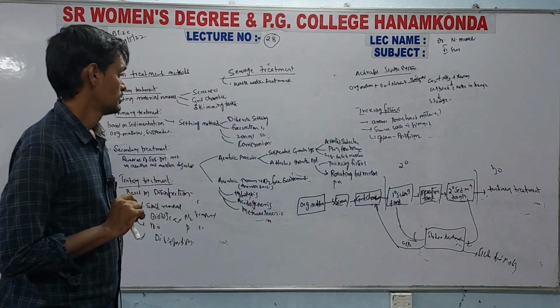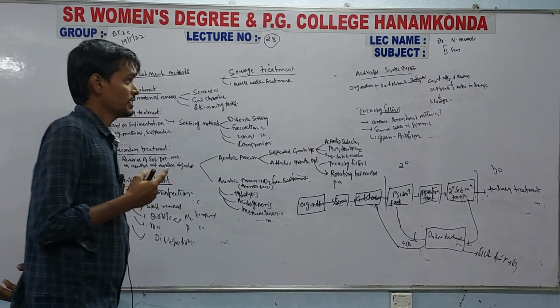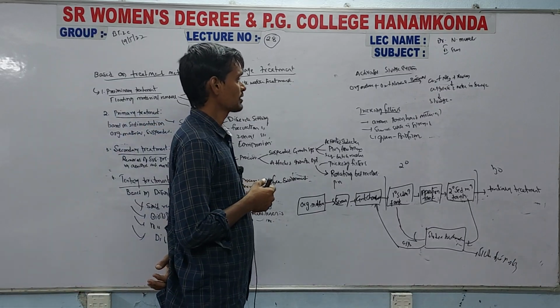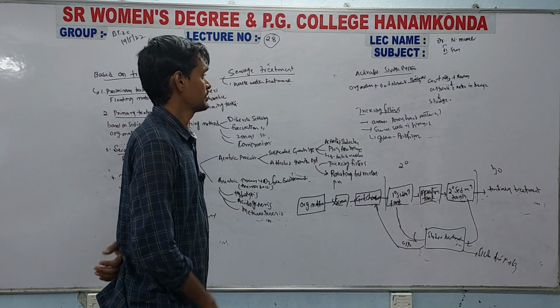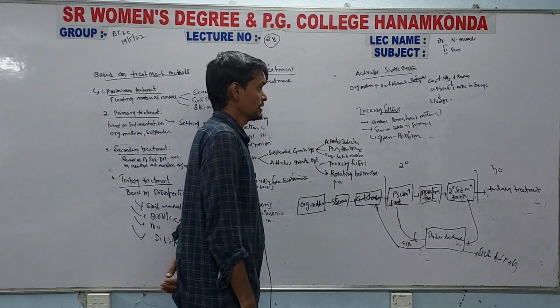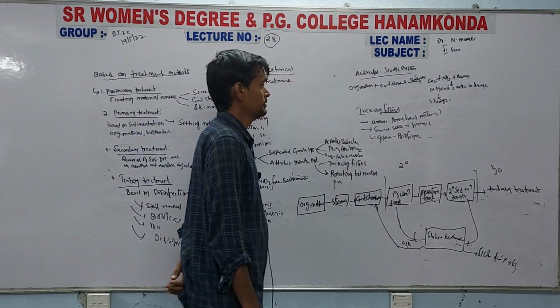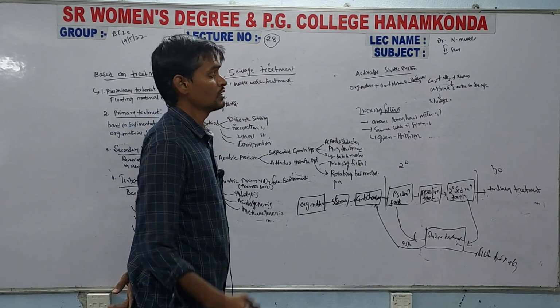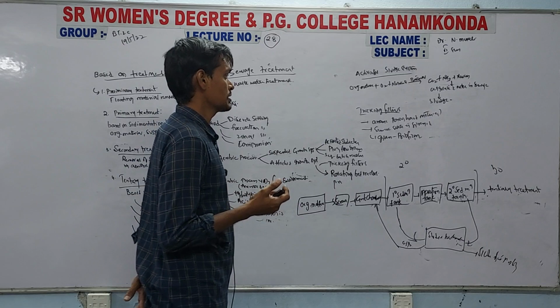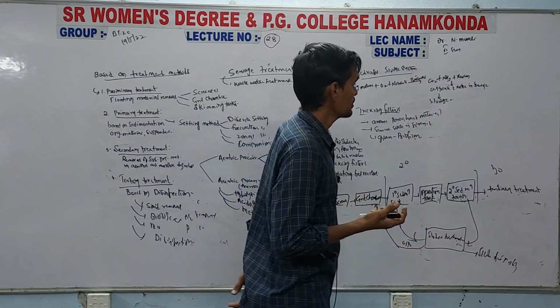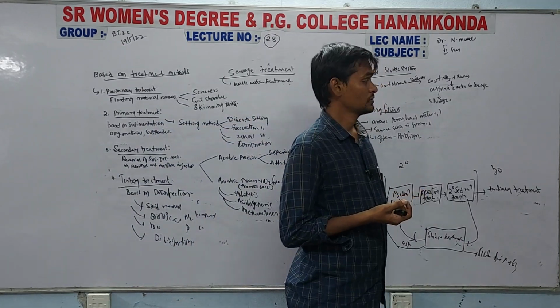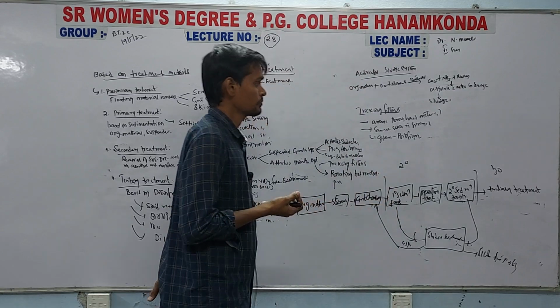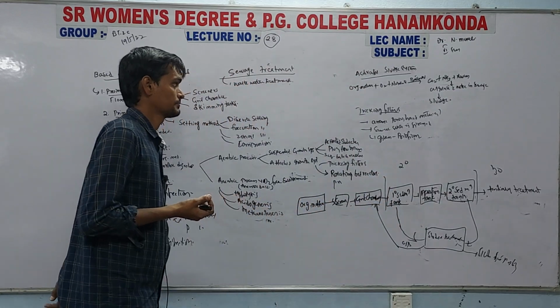Next, if you take the activated sludge system, the organic matter will be treated with aerobic bacteria in presence of oxygen and nutrients. It results in the formation of CO2 and ammonia with new cells. Whatever new bacterial cells are formed will agglutinate in the sewage. That agglutinated product is called sludge.